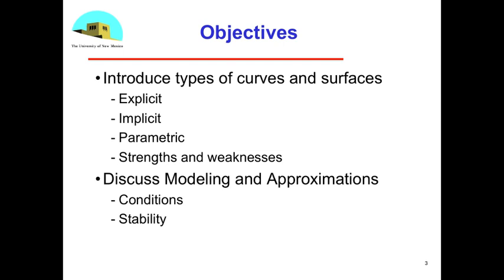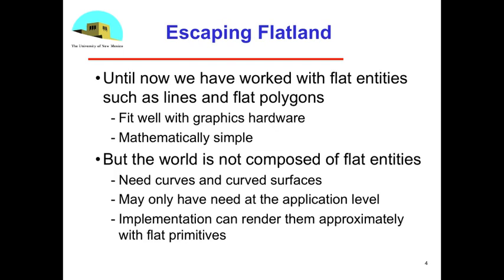And each of those has its own good points and bad points, and that's kind of what we want to discuss in this lecture: see what kind of conditions we need to specify a particular curve or surface. When we start moving around the data that determines those curves and surfaces, we want to have some element of stability. The basic definition is that if you change some parameter a little bit, you move one of the points that determines the curve or surface a little bit, you shouldn't see a very large change in the resulting curve or surface. So that's what we're going to be doing.